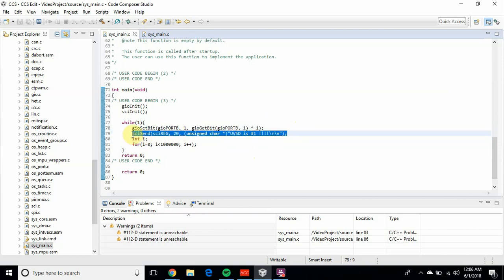One of the first confusing parts is whether you should use send or receive, which are both FreeRTOS functions that are built in for our usage. The best way I can explain this is to think of all the code you're writing as going onto the board itself. So all the code in terms of sending and receiving should be written from the perspective of the board. If you're looking from the board, you are sending information to the computer. So that's why we're using send rather than receive.